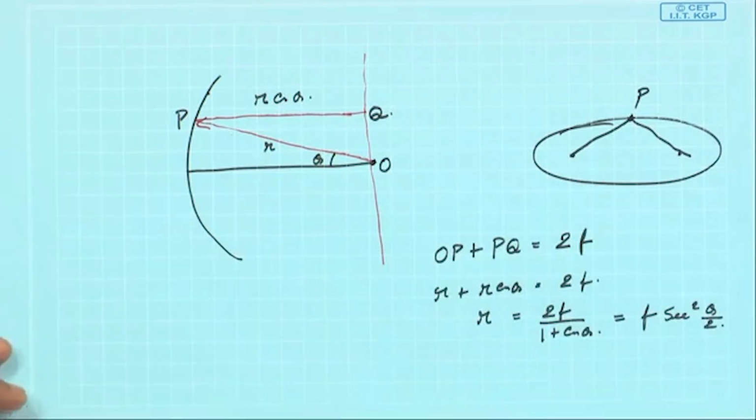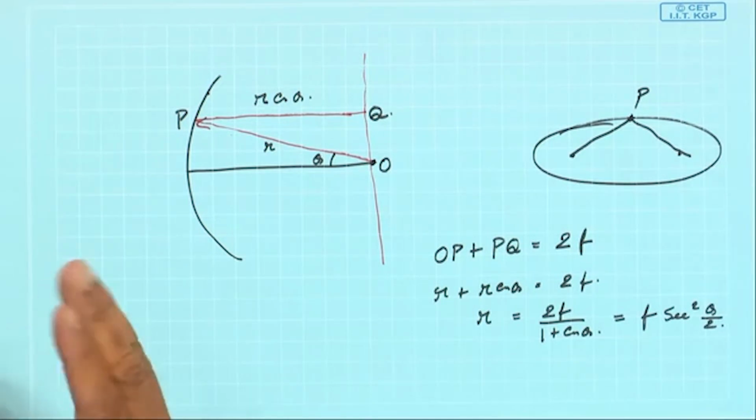Since it is plane waves, the electric and magnetic fields are orthogonal to these. Okay. And for the paraboloid surface, all rays from the focus are reflected to become parallel to the axis. At the edges, the rays are diffracted, but we will neglect the effect of diffraction in this analysis. I already said that the aperture is a plane in this case, which is a circular disc just in front of the surface.